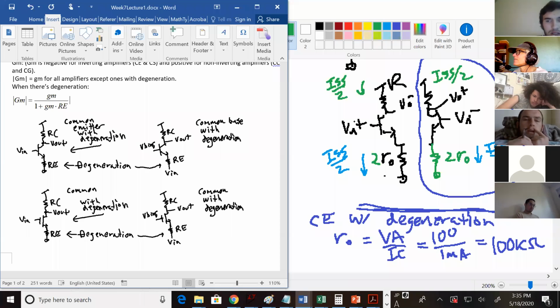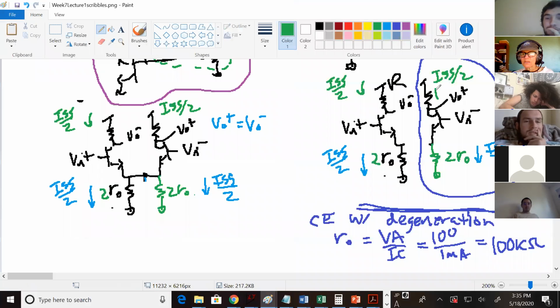Would it be Rout in parallel, or excuse me, the R, I guess, in parallel with RO? Would it be plus 2 RO, or do you not follow all the way down? I get lazy. I just say, hey, it's bigger than RO and be done with it. For the quick method, you can already tell whether it's going to be big or not. Okay, so you have RO in parallel with R. Call this R. RO in parallel with R.